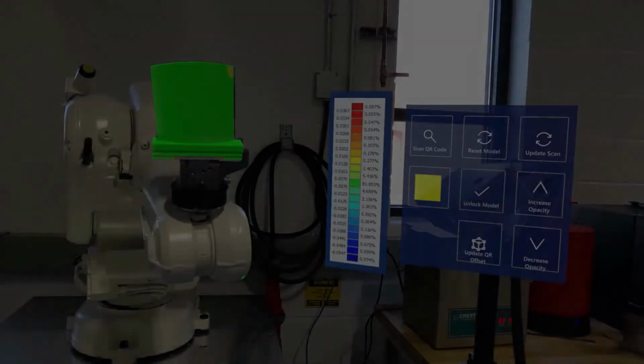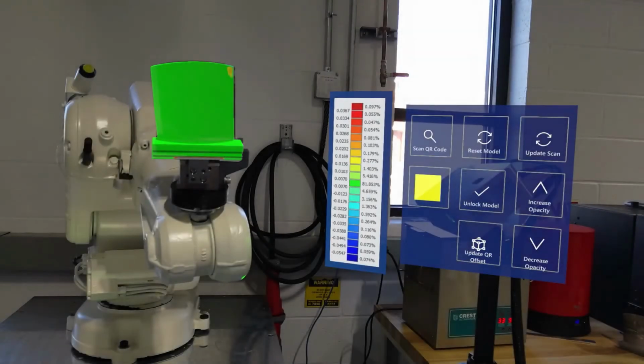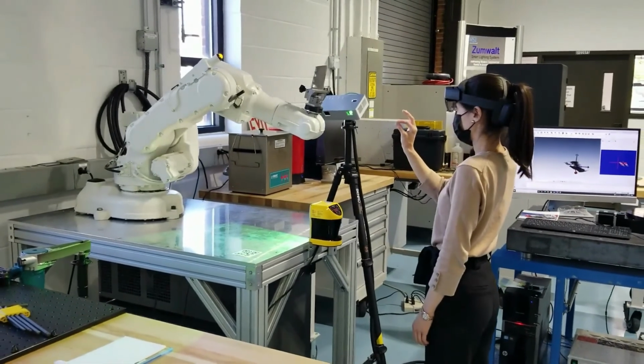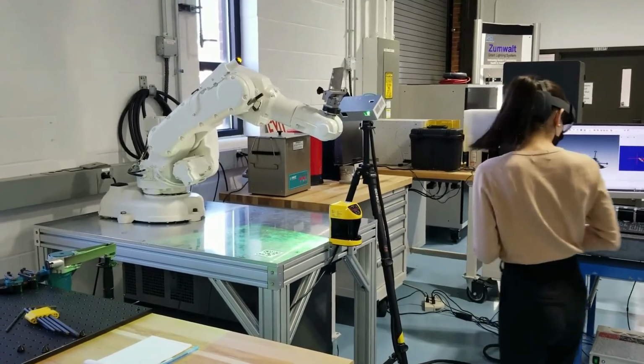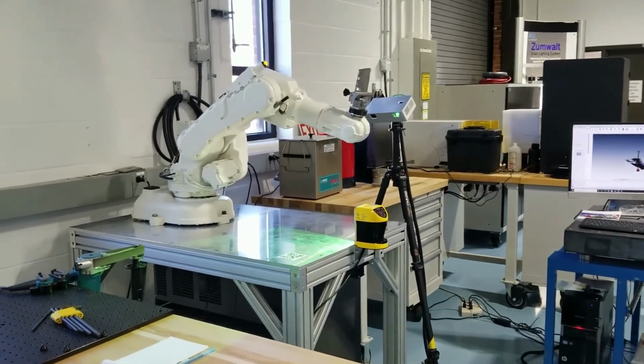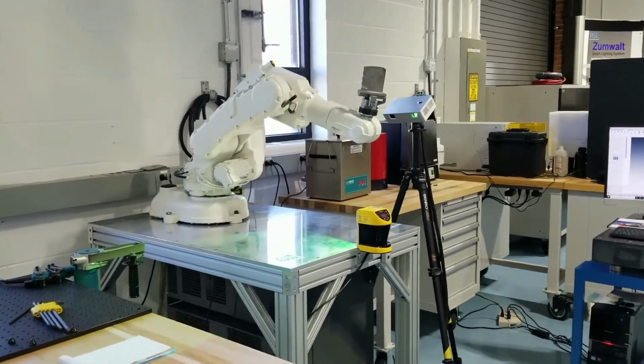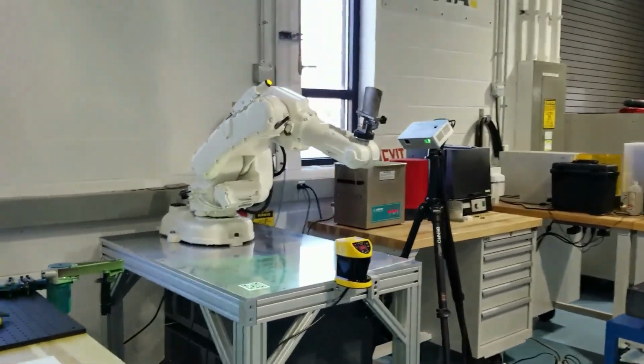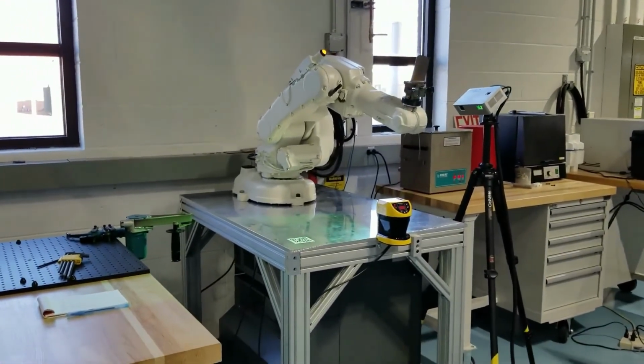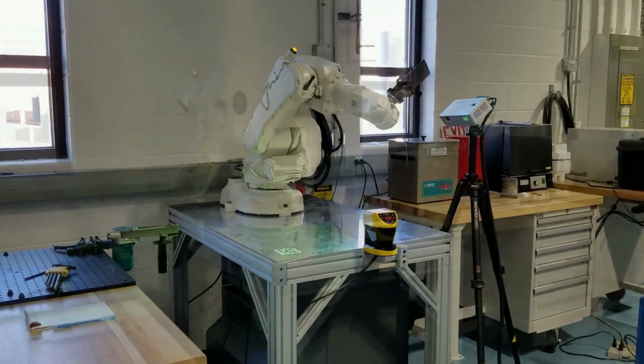And now the scan has been taken, and Kristi's gone back up to the part and is visualizing that data, and you can see that more of the part is green now. We have less of the red up at the top right corner, but since we still do have a little bit of positive deviation, the system is going to continue with the grinding process, again stepping that part in a little bit closer to the grinding belt.